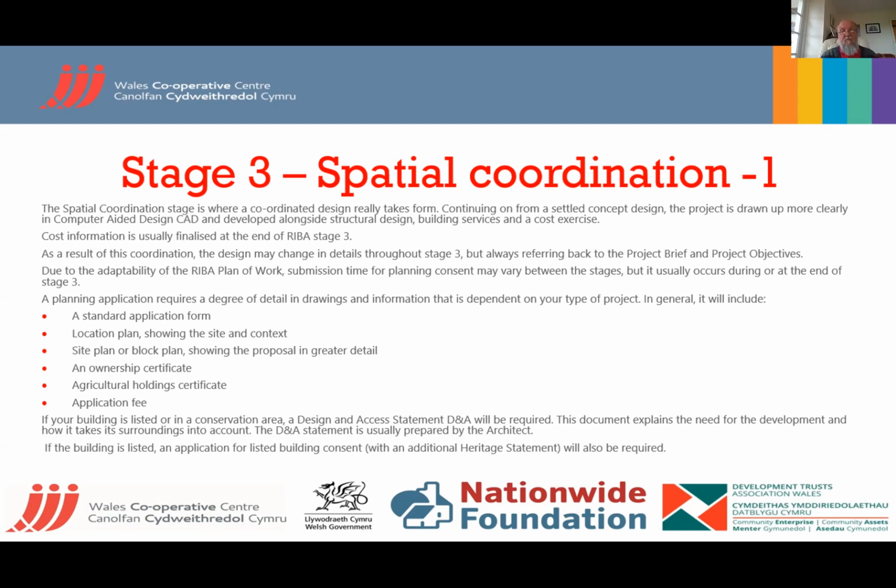And in terms of then doing a planning application, which these drawings are building up to, I don't know how many of you have done a planning application or looked at planning applications, but basically it's a standard form online. You need a location plan at a given scale, either Ordnance Survey 1 to 1,250 or 1 to 2,500.